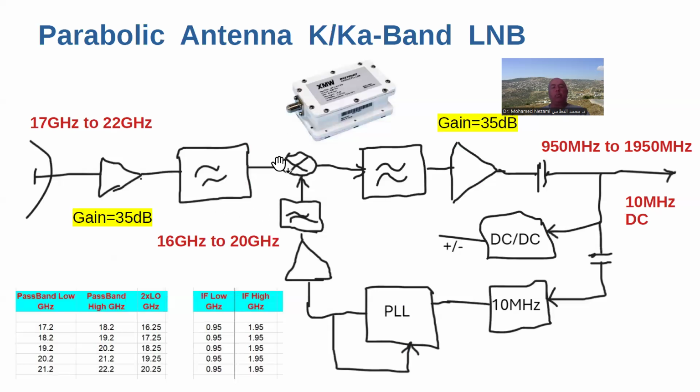So one of the critical components we have is the mixer. What type of mixer, and how we're going to translate the frequency from this band to this band. We chose that as a MMIC part from one of the semiconductor manufacturers. This here is discrete. Like we concluded in the previous part, we're going to build this using discrete transistor MOSFET parts. The IF section in here, we're just going to pick MMICs and ceramic filters.